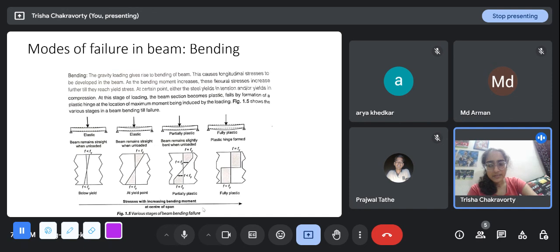While we were doing design of concrete structures, what did we basically do? To design a beam, there were two criteria: bending and shear. They were the only criteria we were designing against. We fixed the dimensions of the section, and we took the percentage of steel reinforcement based on the factored bending moment that we want to design against, and then we checked if the section is enough to take the shear, and we designed stirrups for taking the shear. So that is what we were doing against bending and shear.